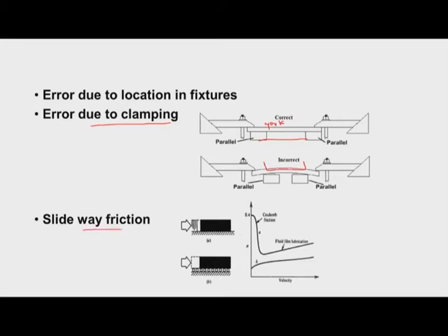Also, because of slideway friction, the movement of the tool will not be proper; there will be jerky motion. Because of that, the surface finish may get affected, or sometimes the geometry is affected.